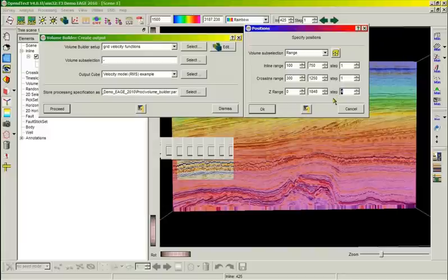Concerning the vertical step out, this one can be more relaxed. We don't need to use the same sampling rate as the seismic sampling rate. And that is quite important because it will control the amount of data that is stored on disk and in memory while working with the velocity volumes. So most often we'll go for a very low lateral step out and a larger vertical step out,